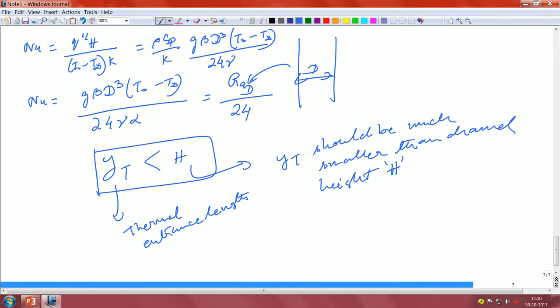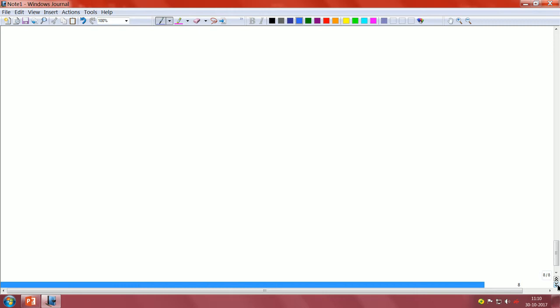Okay. So, can we establish now what will be that necessary criteria, like we did in the case of your forced convection, where we looked at the entrance length dimensions. So, now for Prandtl number greater than 1, once again the two limits we are going to apply. So, yt into Rayleigh number with respect to yt, remember that this is almost equal to, the scale is actually d by 2 when the entrance length actually ends, because delta becomes of the order of d by 2.